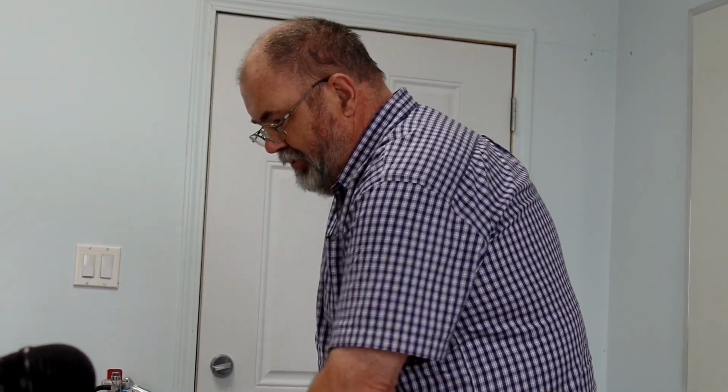And there's nothing to say that I can't hook up 2 T connectors, 5 T connectors, 8 T connectors, and take out a whole series of frequencies if I want to. Okay? So this was an example of just taking one frequency out. And all I've done is I've taken an open circuit, used the T connector, and found the frequency I want, and went snip, snip, snip, snip until it's gone. Cutting a quarter wavelength like this is so much fun. You cut 1 millimeter off and throw it away and get a new cable. Oh, it's very picky, is it? Oh, get the cable stretcher out, yeah. Okay. It's really handy for that, for eliminating an unwanted station.